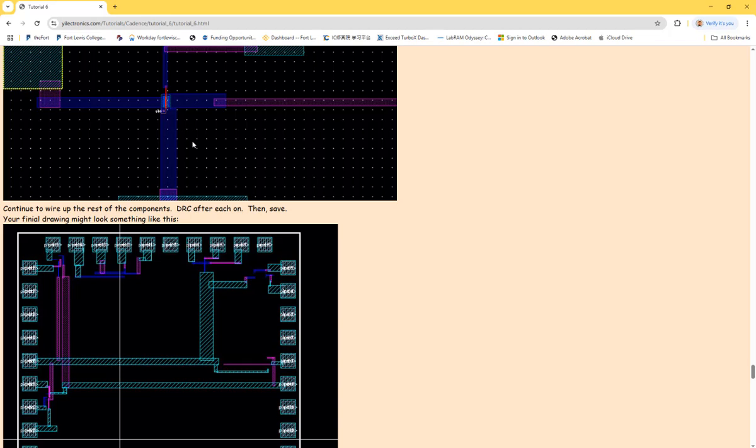So the thing is, most of the PDKs, or process design kit, it's called PDK. Most of these tools or libraries are IPs of the company, so nobody can disclose them. But really interesting, NCSU is North Carolina State University. Since many years ago, probably like 15, 20 years ago, they released all these PDKs. I don't know if you can fabricate chips using their PDKs, or they maybe just fake PDKs for educational purposes. That's why we can use it.